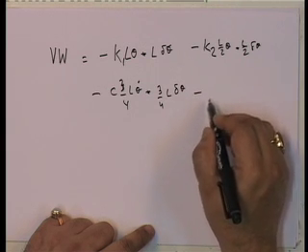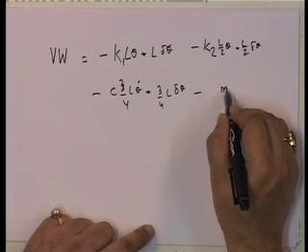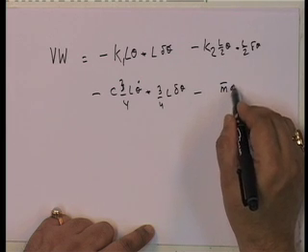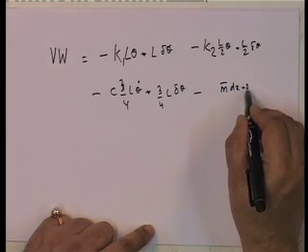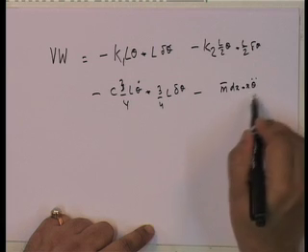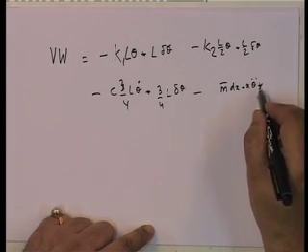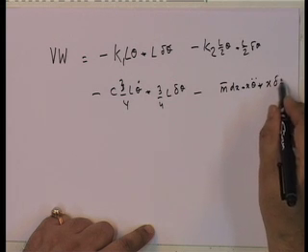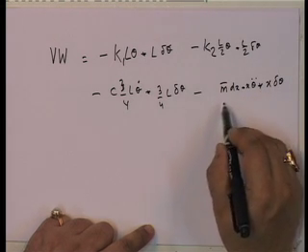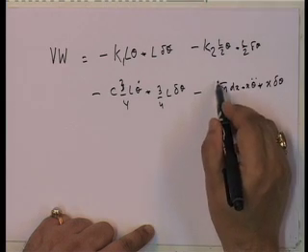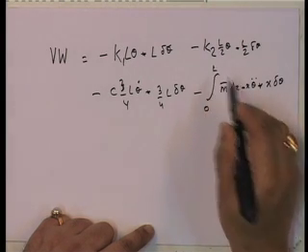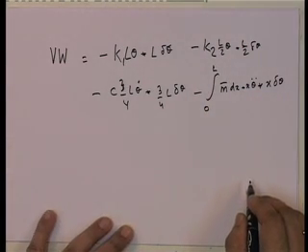Remember that this is the real force, and the force is multiplied by the virtual displacement of that particular point. Then we have the following, which is m bar dx into x theta double dot. This is the inertial force, and this into x delta theta is the work done by the infinitesimal length, which obviously has to be integrated over the whole length.